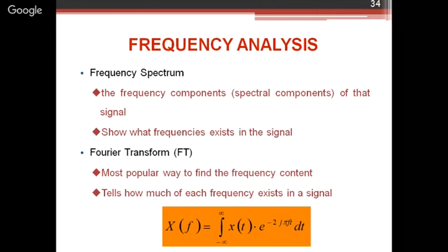This is called the forward kernel. So they are very important, and Fourier transform is one of the very popular transforms, but you cannot apply your Fourier transform for the non-stationary signals. You can apply it for your stationary signals where data is not changing, because Fourier transform works globally. Once you apply Fourier transform, it will act on the entire signal at one particular instant of time. You cannot check or analyze the separate parts of the signal in different time spaces. So this is one of the disadvantages of Fourier transform, because in the real-time